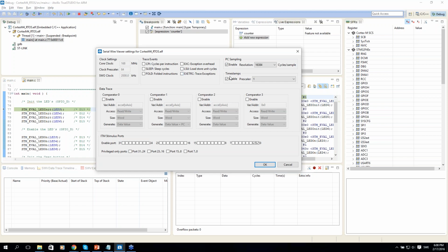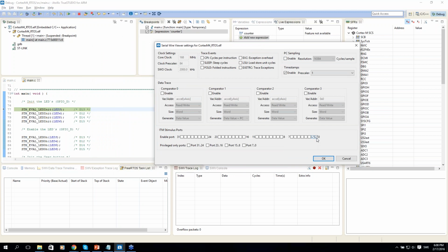with this tracing technology. And the first one is to use the old classic Printf debugging, but instead of hooking up an RS-232 terminal and messing around with adding code for that, instrumenting your application and having these cables consuming I/O pins, etc., I'm going to just use what's called ITM ports. There are 32 available ITM ports in your CPU core, which can be set to redirect printf traffic back to your debugger through the common debugger interface, the USB cable in this case, from the ST-Link to the PC.